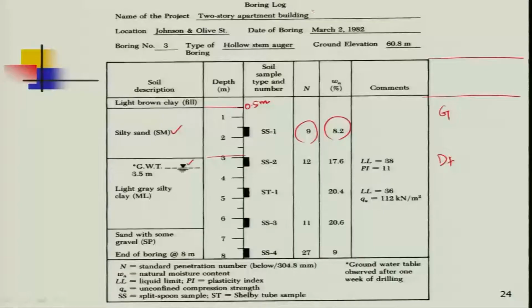That does not mean you put a shallow foundation of 10 meter by 10 meter, as the cost of the foundation would be much more than the actual superstructure. There are limitations, and some experience and judgment must come into the picture. Then what kind of loading is coming to the structure; the design engineer will do all the calculations and take a call. Look here, this is only a 2-story apartment building.